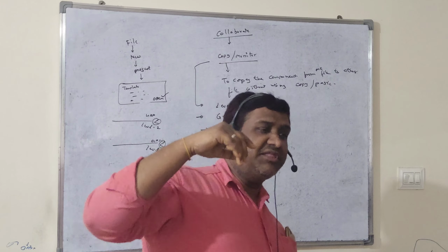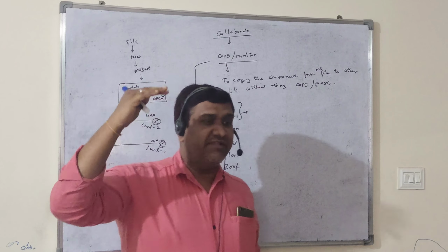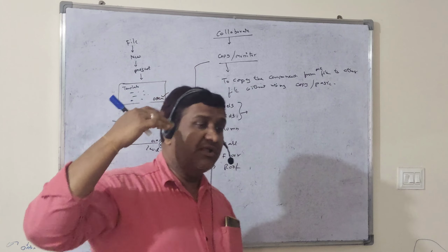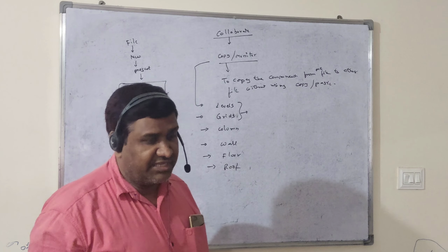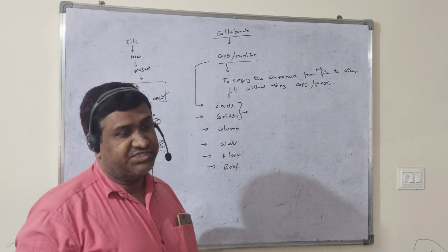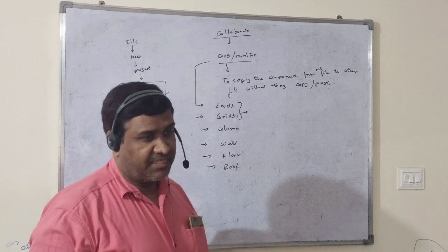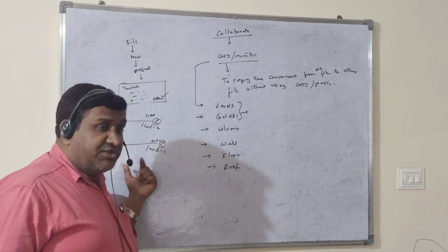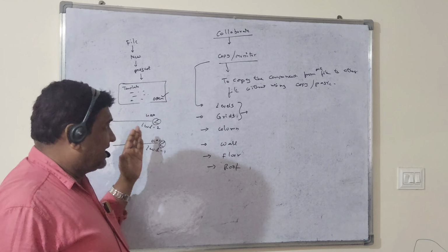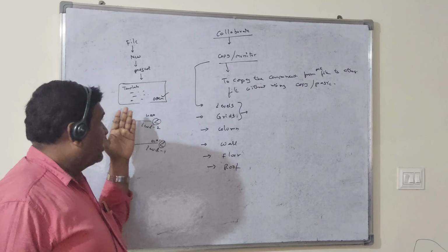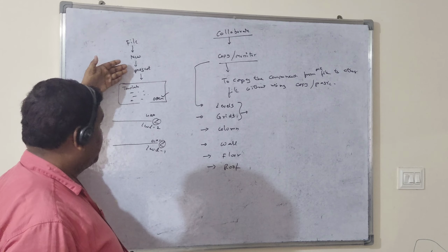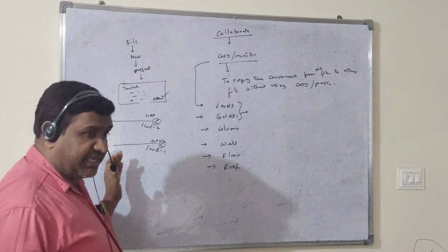Apart from the 2 levels, if the project has some 10 floors, 20 floors, 50 floors, you manually create one level each. Am I right? Previously you did the same thing for the project I gave you for practice. So if you are going to take the levels and grids from another file, you have to go to the File menu, New Project, new template file, and take it.